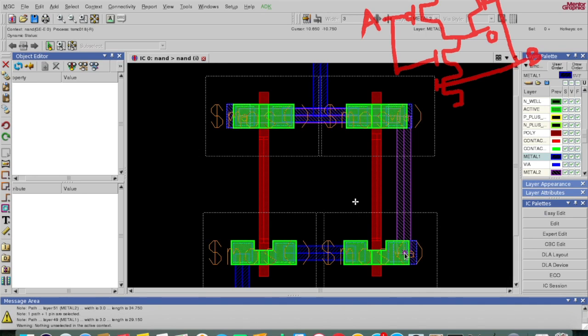Okay, and normally I should check DRC all the time, after every drawing, to see whether I'm violating any rule. So now if I check the DRC, two errors will definitely come, like substrate contact is missing and well contact is missing. Other than that I want to see whether there is any error or not. So I'll check it. It is processing.